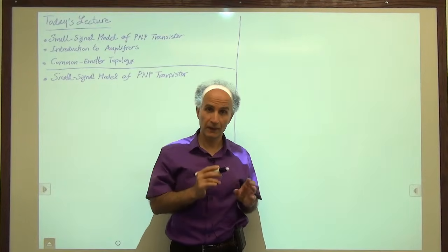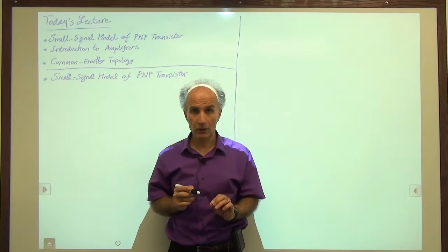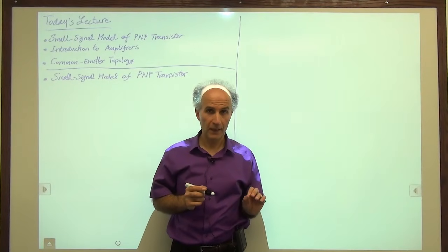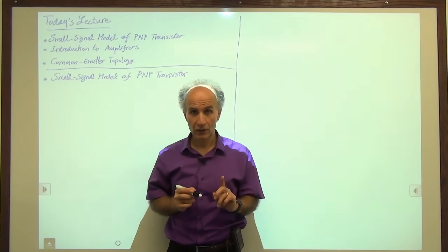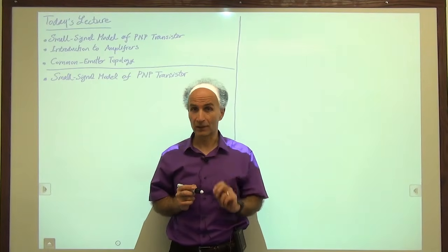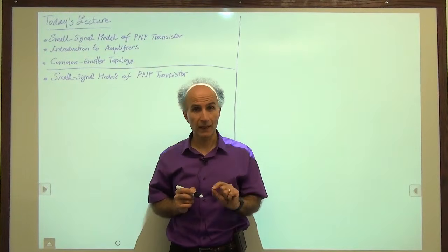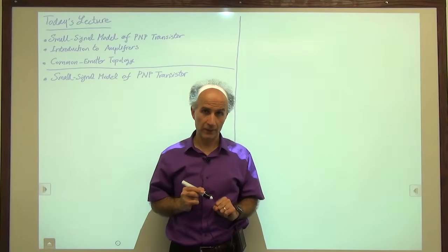So without going through the details, I will just state here that the small signal model of the PNP device is identical to that of the NPN device. Identical. I repeat this because students often make mistakes about the small signal models.